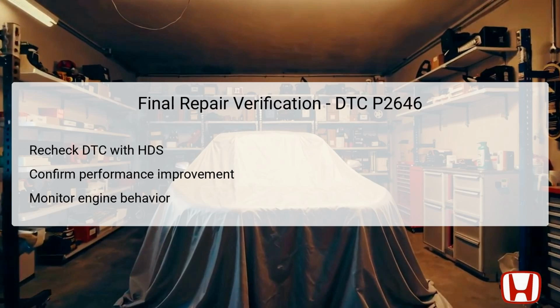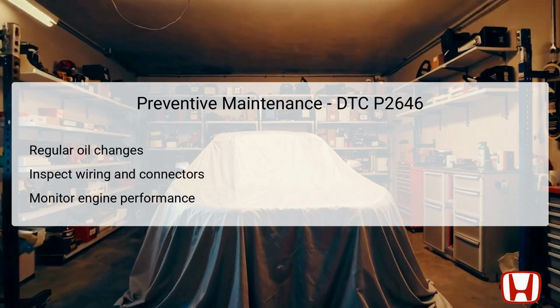Additionally, confirm that engine performance has improved, ensuring proper engagement of VTEC under various driving conditions. Monitoring the engine's behavior during a test drive can provide final confirmation that the issue has been successfully resolved, safeguarding against potential future occurrences. To prevent future occurrences of DTC P2646, adopting a proactive maintenance routine is highly recommended.